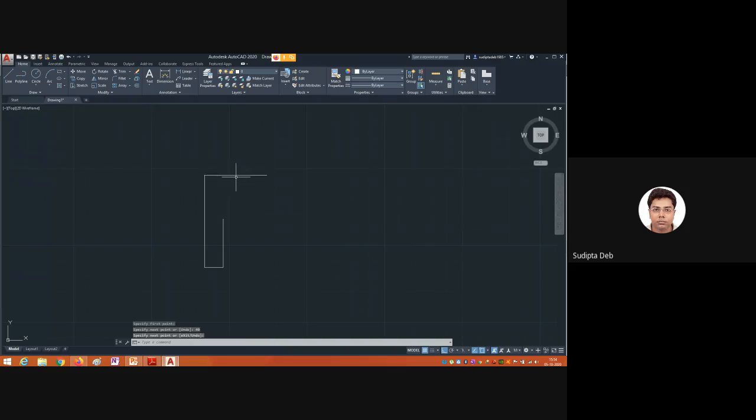Now I can specify the center line. For this, we have to turn on midpoint to find the center. Now it will show the center. Now let me consider the circle. Command is circle, C, enter. This is the center. I am taking the round section. Let me trim out the lower section that is not required.